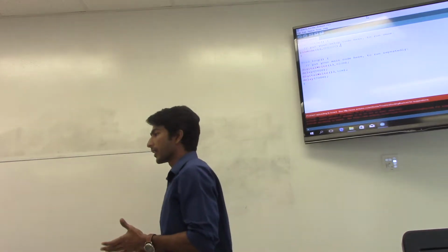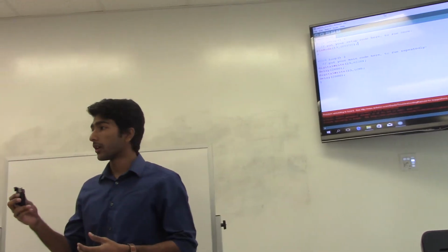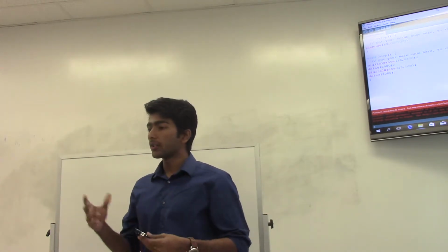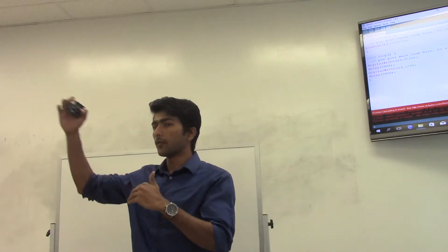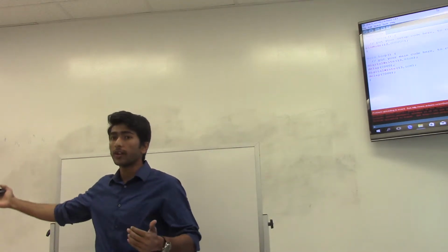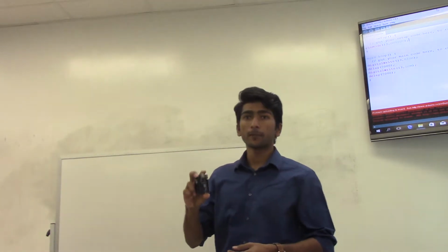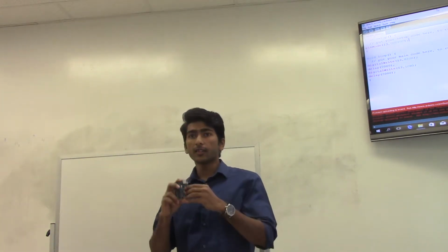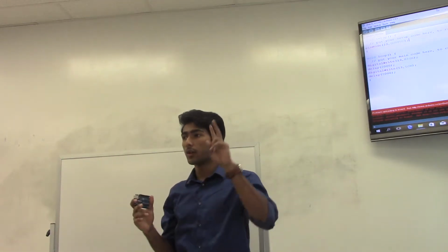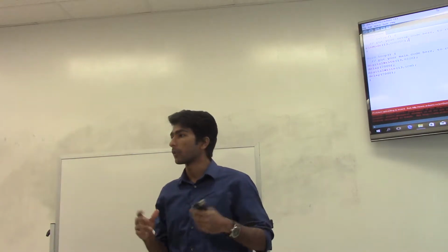Okay, an analog signal is nothing but a continuous signal. So when you are talking about voltage here, Arduino works on 0 to 5 volts, so it's that range. So analog signals generate voltage between 0 and 5, so you can set it to 1.5, you can set it to 2 or 2.5, 3, 4 and 5. But when you are talking about digital signals, there are only 2 states. So either you can set the value to 0 or 5, but not in between. So there are only 2 values for the digital pins, and there are continuous values for the analog pins.